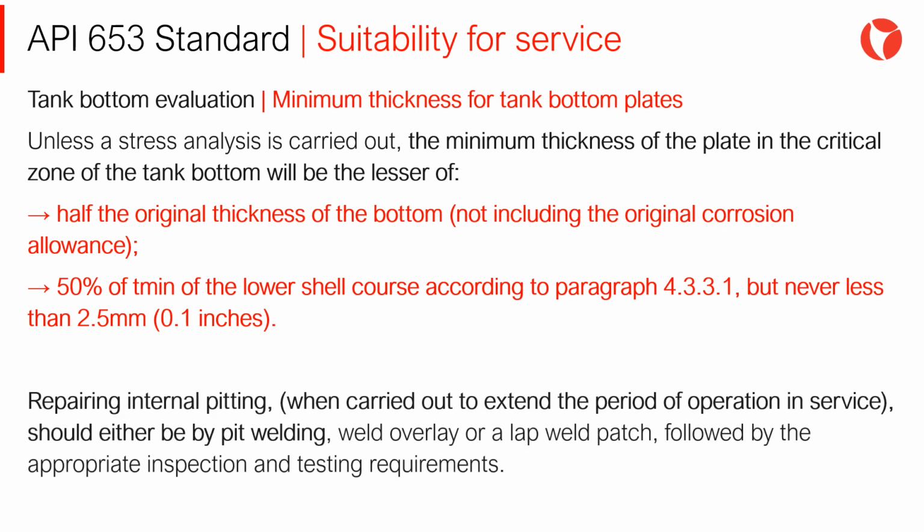Repairing internal pitting, when carried out to extend the period of operation in service, should either be by pit welding, weld overlay, or a lap weld patch, followed by the appropriate inspection and testing requirements.